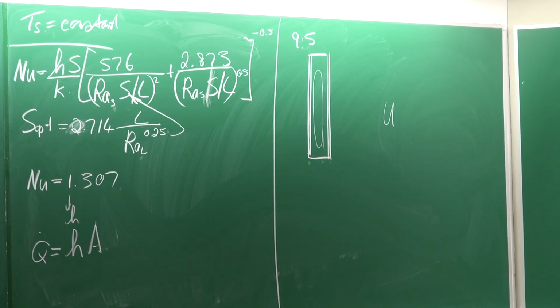But typically, if you look at single glazing glass, 3 millimeters, then the U factor will be about 10. Okay, the U factor will be about 10. If you look at triple glazing glass with a 12.7 millimeter airspace, then the U factor goes down to about 1.19. Or if you use argon inside, then it would go down to 0.8. So from 10 to 0.8.